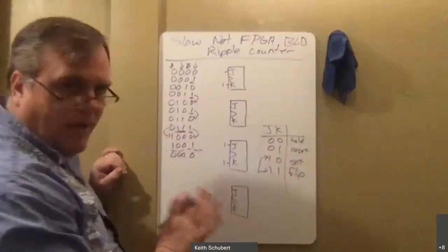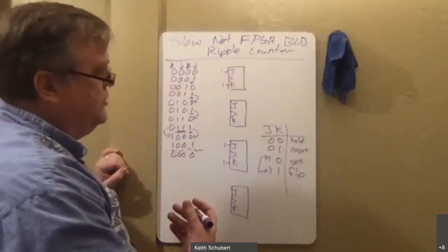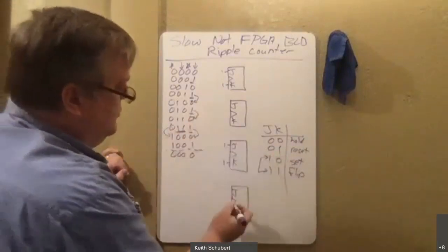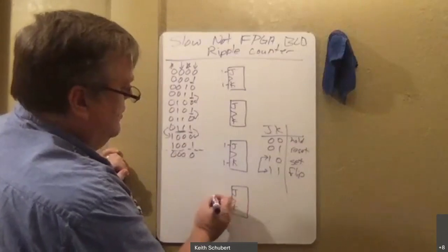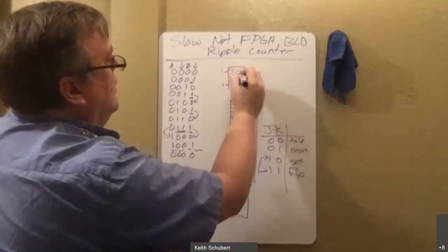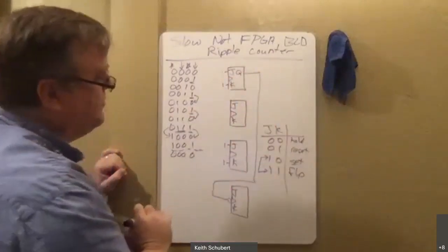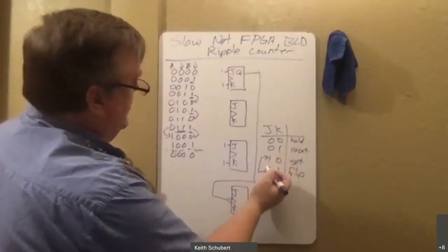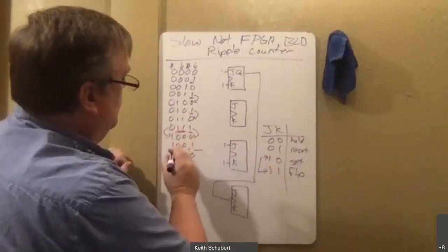Now, I'm not going to use my normal excitation table here because I'm kind of doing a human observation. I want this one. This transition flip means take the clock down. This transition, I need for that spot when the previous two are 1, 1.